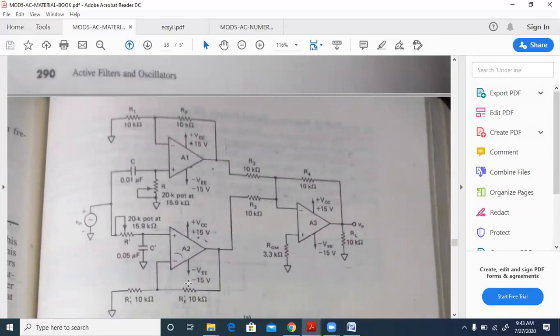High pass and low pass are connected in parallel. You can see that one is above the other. We are giving input here and they are connected in parallel for band reject. For band pass, they are connected in series, high pass and low pass. For band reject, they are connected in parallel and then they are summed, added together. Whenever we say connected in series, it corresponds to multiplication, and whenever we say parallel, it just corresponds to addition, okay?